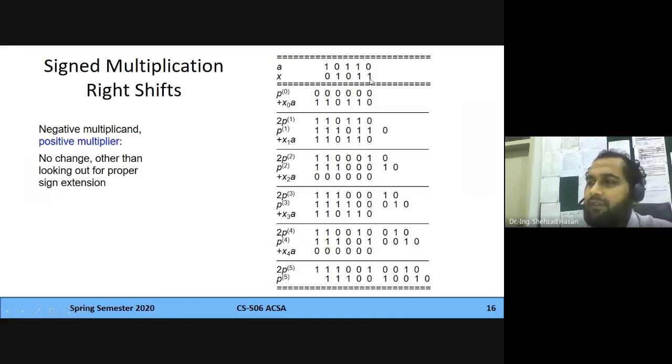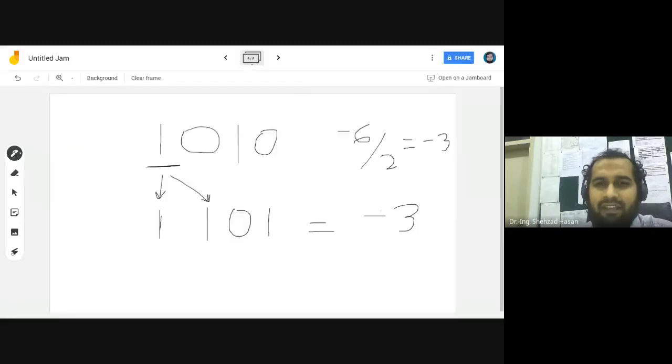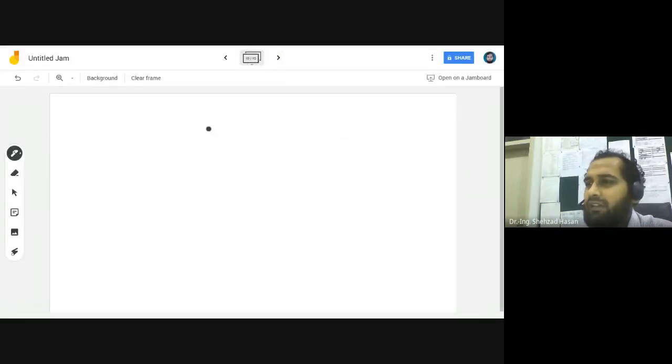Okay, let's start. So this is one. We are going to have a 10110. So we have written 10110. Now, this one is actually a sign extension of that. If you have got a negative number, you are going to extend it by having another 1 over here as its sign. If you have a 0 over here, you are going to extend the sign with 0. So if you're going to store a number in a bigger space, you just extend that sign. I think it's known to all of you.